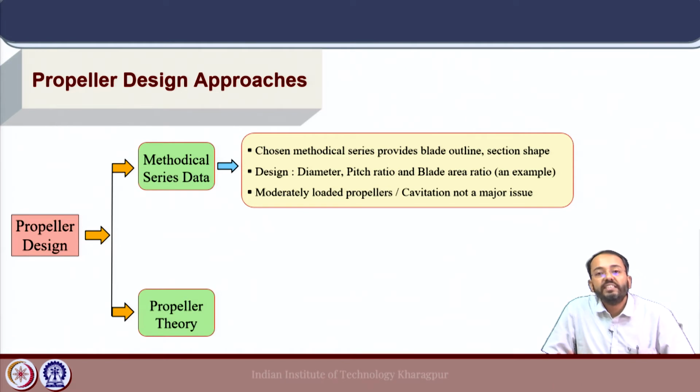So, these series data can be suitably interpolated, and for specific geometrical characteristics of the propeller blades, a suitable series based propeller blade design can be obtained for a good range of running conditions in moderately loaded propellers.